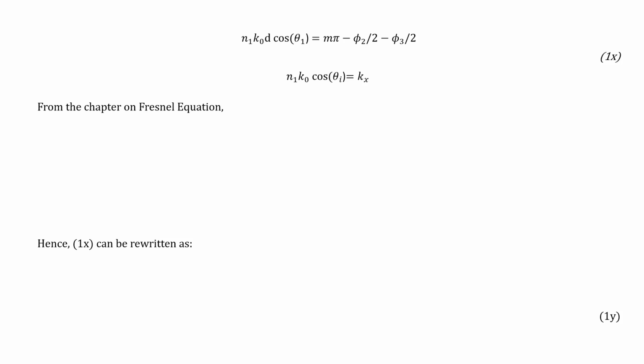And similarly, in the horizontal direction, we just need to do this. And this is the wave number in the z direction. And the z direction is beta, the same beta that you can see in other textbooks. I mean the wave number in the direction of propagation, and in this case you may have heard this is the propagation constant.